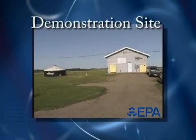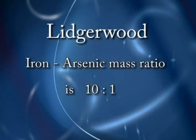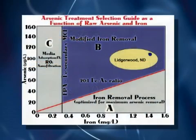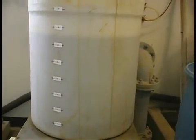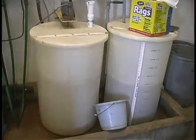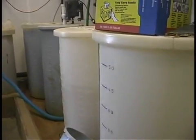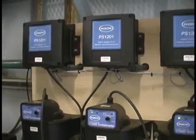The EPA demonstration technology for this system was a modification of the existing system to add more iron. The natural iron to arsenic ratio was only about 10 to 1. Again, this ratio places the system in Zone B on the chart. Therefore, the project included dosing the raw water with ferric chloride to increase the iron to arsenic ratio to 20 to 1. To assist in the filtration process, an additional filter aid polymer was added. Turbidimeters were installed on the filters to monitor the treatment process.